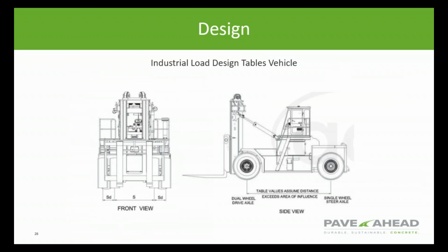When you look at the loading for a typical fully loaded 18-wheeler, the load is spread out over a much larger area and among those 18 wheels. With equipment like the forklift shown here, there's a heavy load, but it's spread over fewer tires in a more concentrated area. The result is that these more concentrated loads can cause more damage to the pavement than semi-trucks.